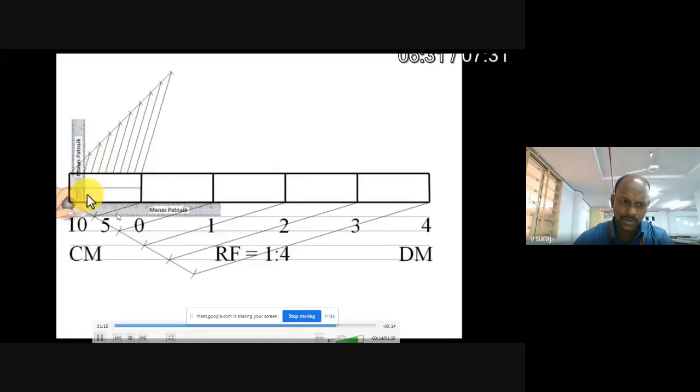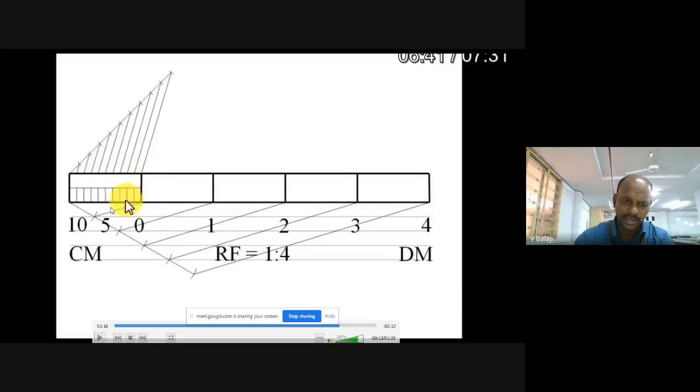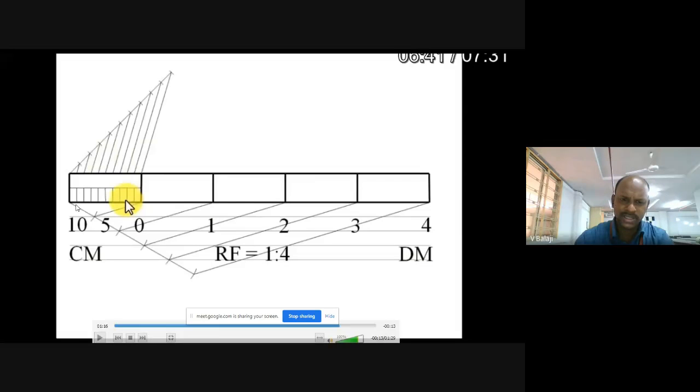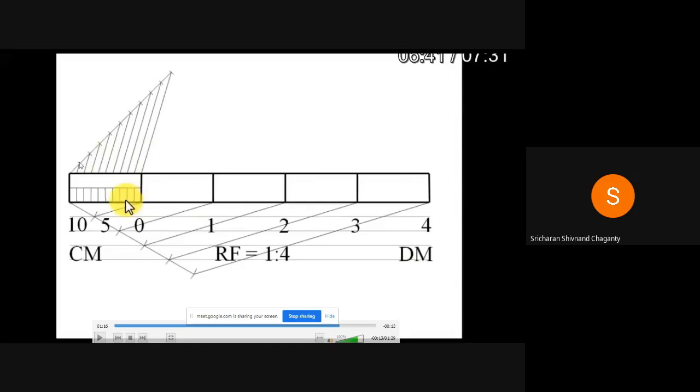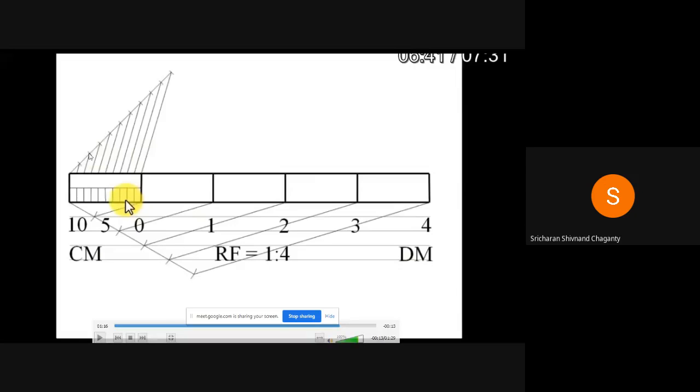So like that you can draw perpendiculars. Can you explain again, sir? The first part, what we are doing is because 1 decimeter equal 10 centimeters, I have taken an angular line, and 10 equal arcs I have drawn. So I have divided. That angular line can be of any angle, what we have discussed in the previous classes. Angular line can be any angle. Here also any angle.